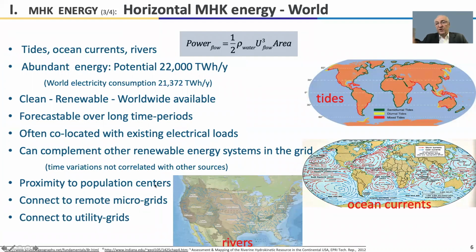Hydrokinetic energy, there is vertical in waves and horizontal in tides, currents, and rivers. And we're talking today about horizontal hydrokinetic energy. It is proportional to velocity cubed and to the area swept by the devices that we use to harness that energy. It is clean, it's renewable, it's worldwide available. It is easy to forecast over long periods of time, and it's collocated with existing electrical loads.